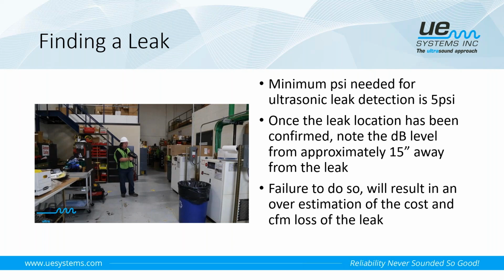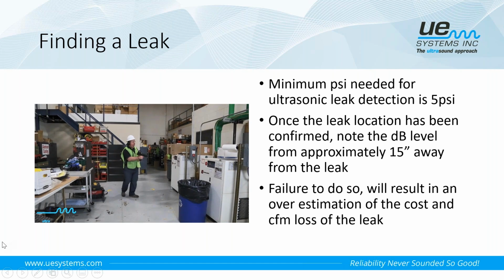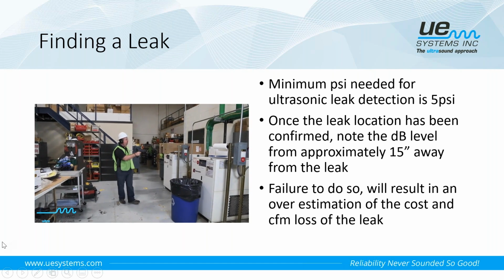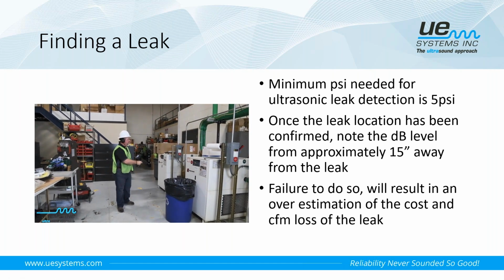and the sound will lead us in the direction of where that leak is coming from. But the whole time that we're scanning, we're going to be adjusting the sensitivity, and we're finally going to be able to pinpoint exactly where the leak is coming from. And then once we've isolated that leak, that's where we're going to back away approximately 15 inches. So that's what you'll see here in the video. You can see that we're just sweeping the area left to right, up and down.